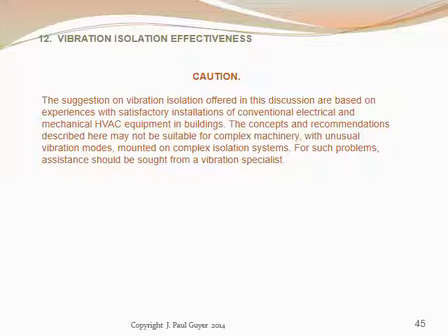If the pump impeller has 10 blades, for example, the driving frequency would be 300 hertz and the ratio of driving to natural frequencies would be about 100. So the isolator would clearly give a high degree of vibration isolation for impeller blade frequency.